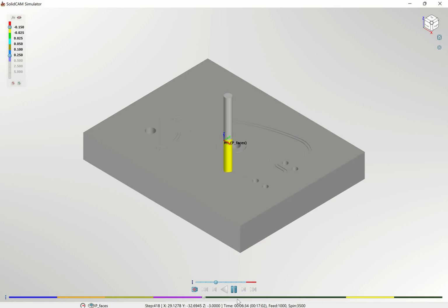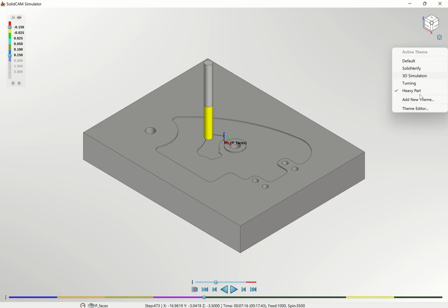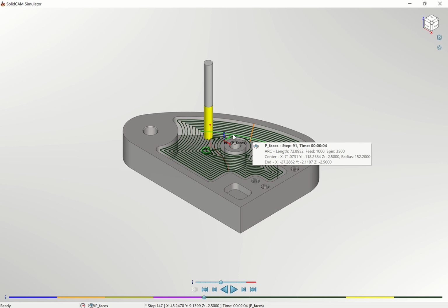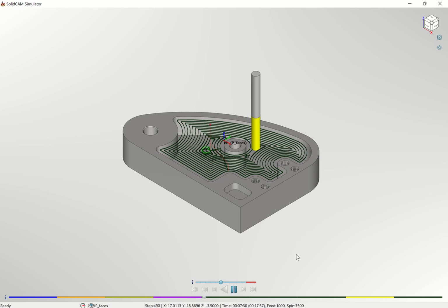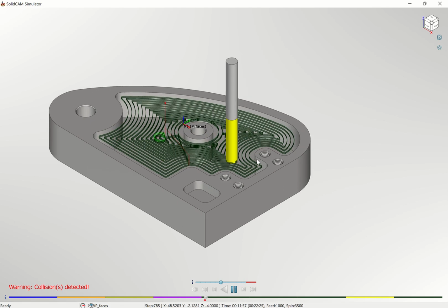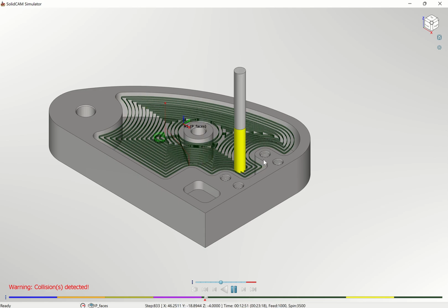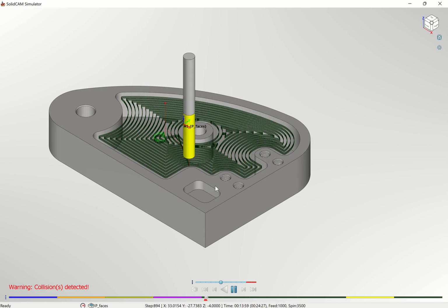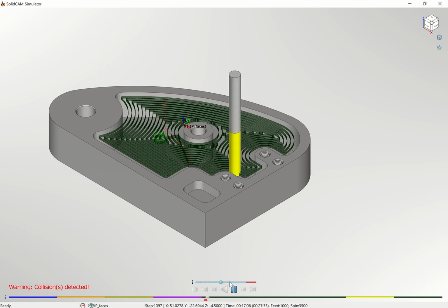You see, you can pause and change the simulation type you want, or this 3D simulation. You can pause, change the simulation you want, and if you click run, it updates. So this is what it is doing. It has already done tapping, pocket, and these are the tool parts. So you're able to do a simple simulation to see what it will give you.